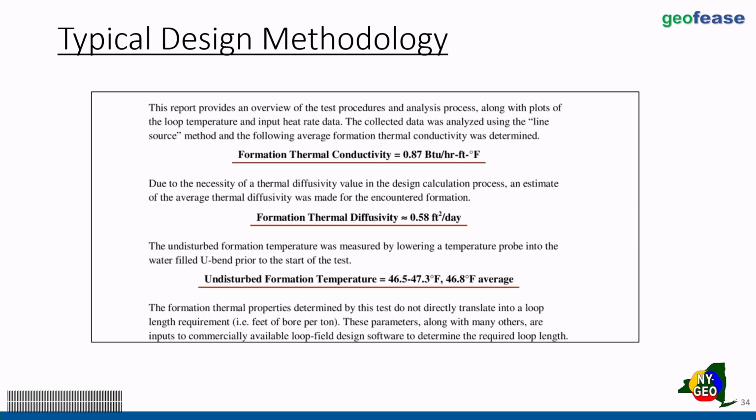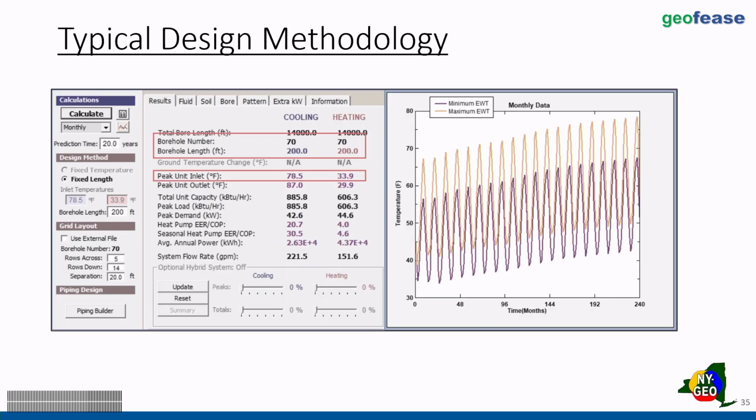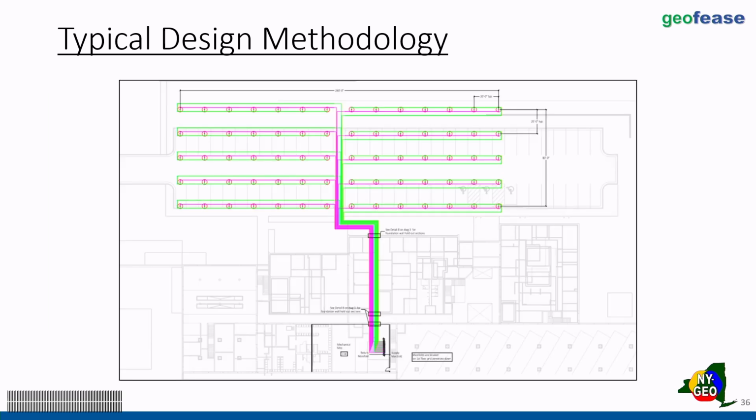Try and really understand the heat loss and heat gain. Then you go to site, you do your thermal conductivity test, try and understand the thermal properties of your particular site. Use your favorite ground heat exchanger sizing software, whether that's GLD or TRANSYS, or pick your favorite. But underlying all of these softwares are two main algorithms or equations. One is called design day, and the second is called G function, and they're theoretical. So in nature, they have some limitations. You do your AutoCAD drawings, and away you go. Right? You go on to the next project, or you help with commissioning and actually constructing it.